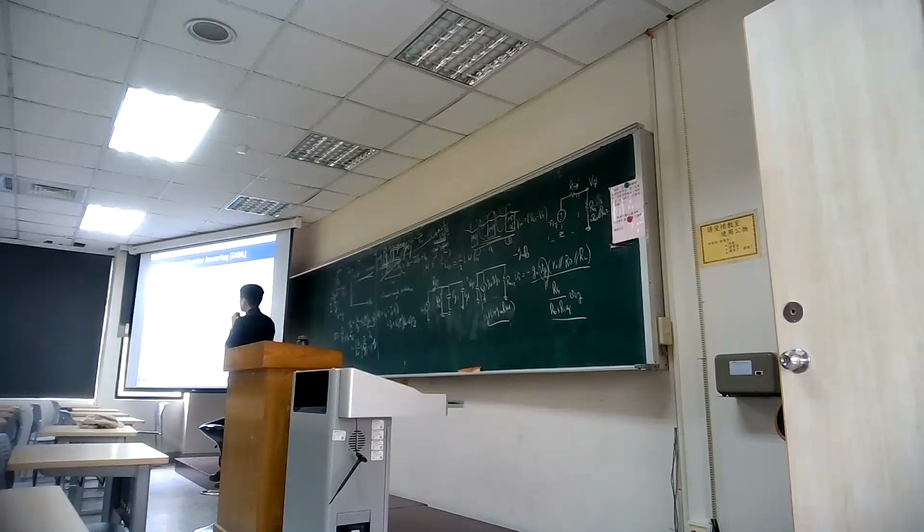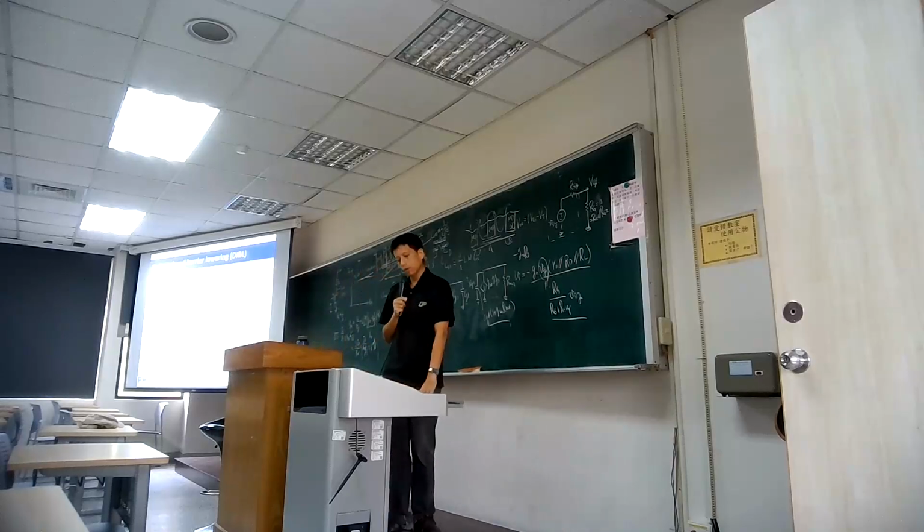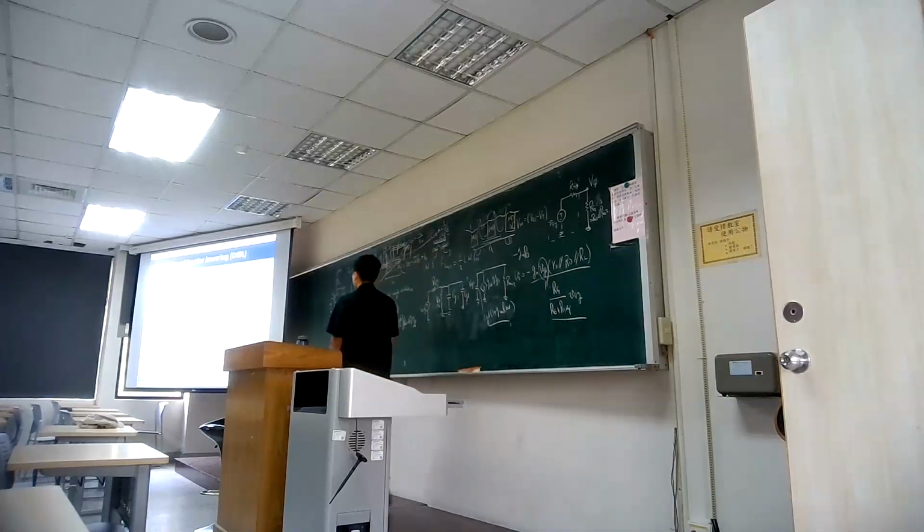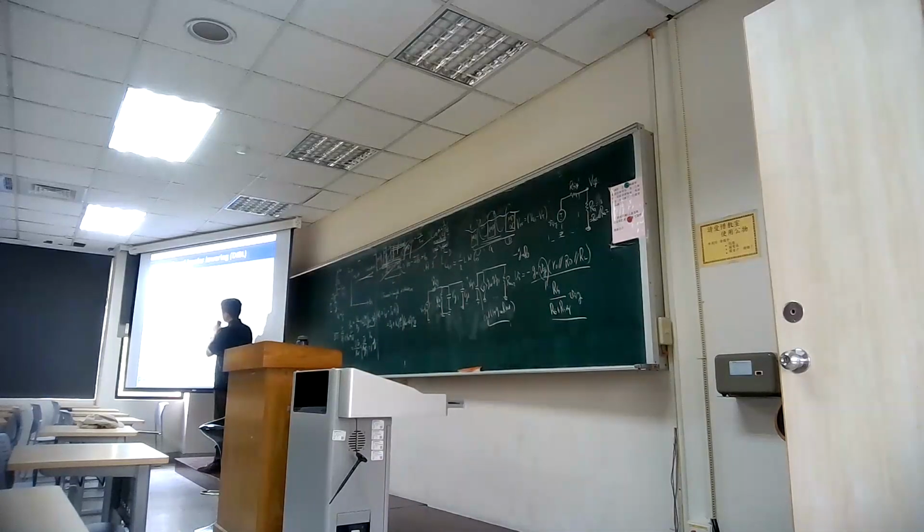That is the basic idea. So you get a certain leakage current increase, especially from the lowering of the threshold, because the subthreshold leakage current is controlled by this voltage. But there will be some degraded performance. So this is the main diagram to show.